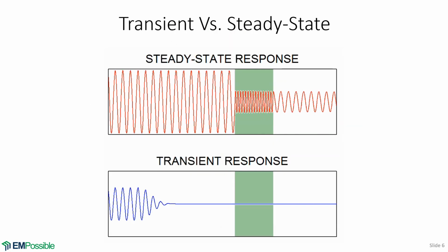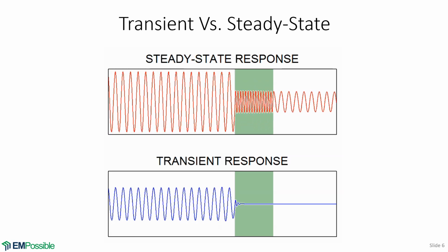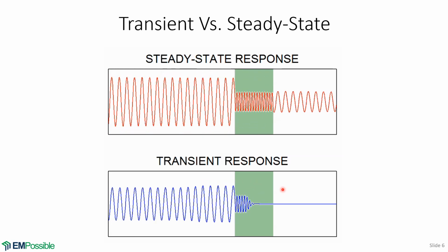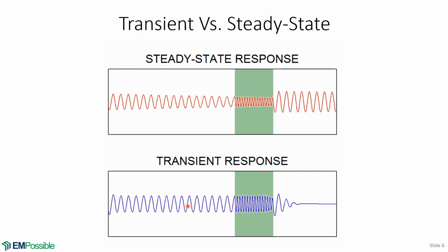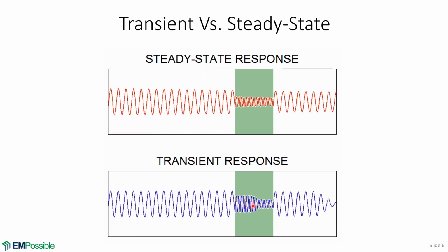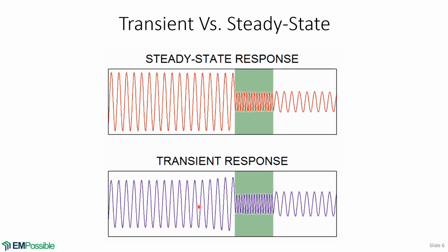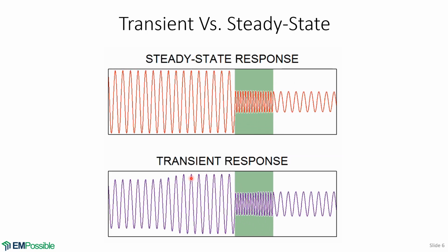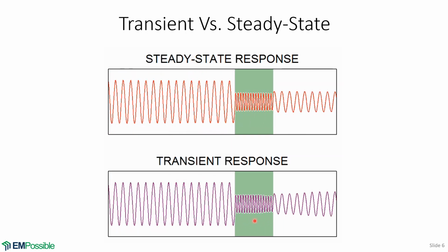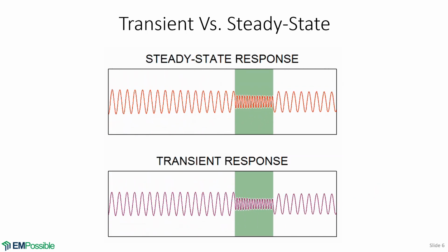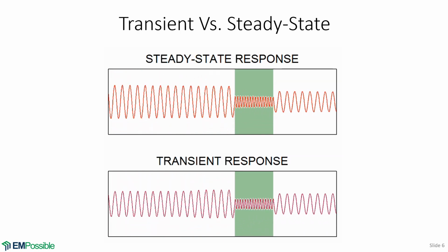So let's think about steady state versus transient response. This is an electromagnetic simulation. We have a slab of dielectric in air, and we've illuminated it with a pulse. So imagine turning on a flashlight. And some of that flashlight has now gone in and reflected. Some is reflected here. This up-down is the standing wave. And now you can see that the amplitude is a little bit uneven. That's because some of what reflected is now traveling backwards. But as we let this run and run and run, we have this flashlight from the left has remained on.